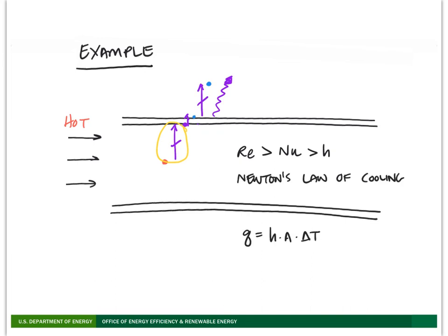In this calculation, as long as we know the temperature difference, in other words, if we know approximately the temperature of the air inside the duct, which we can probably get a good feel for based on a thermostat setting and some information about our HVAC system, and then we know the temperature of the other system, which is the outside attic or crawl space temperature, we could probably estimate that pretty well based on weather conditions that we can look up.